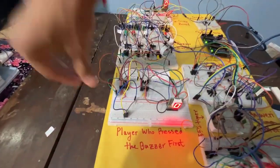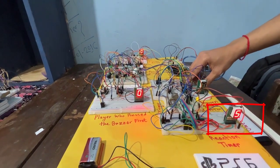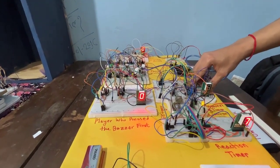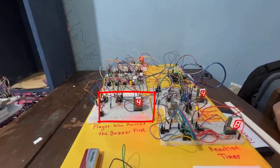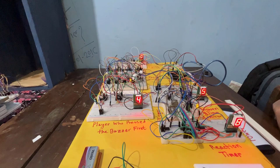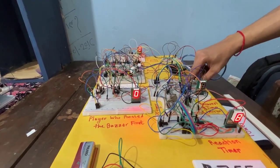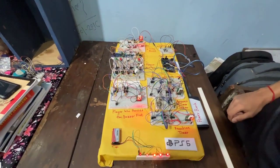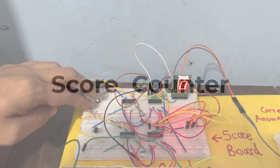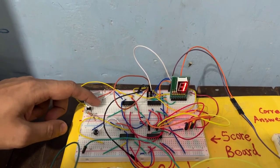After asking a question, the counter starts counting up to 10 seconds. Say, within the time a player has pressed the buzzer first, that number will be shown at the display and other players will be blocked. Simultaneously, the reaction timer will be paused and the answer time counter will be on and count up to 10 seconds, which permits the player who pressed the buzzer first to answer the quiz within 10 seconds. If the player answers correctly, points will be added to the score counter. Point adding, point decrease.